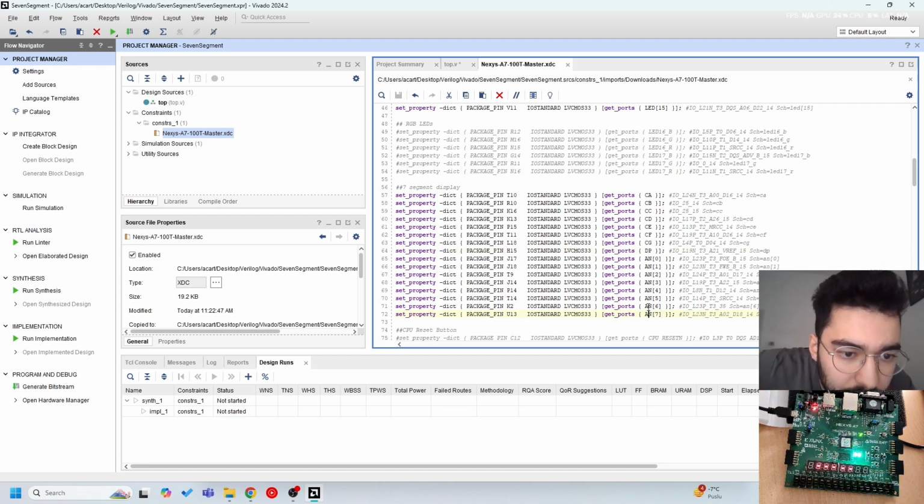And here you will see that we only have how many? 8 here, 8 here. We only have 16 pins for controlling 8 7-segment displays. And you might think that this is not enough, as if you remember, we had 7 pins per 7-segment display. So at the digital lab, the FPGA we used had 6 7-segment displays and 7 pins for each, resulting in a 42 pin count.